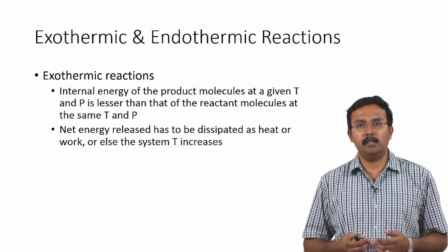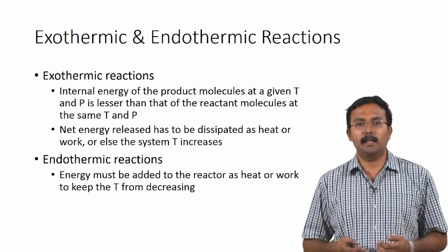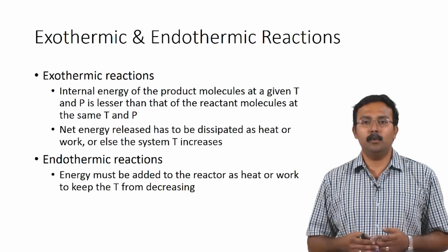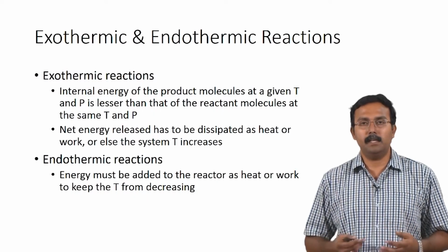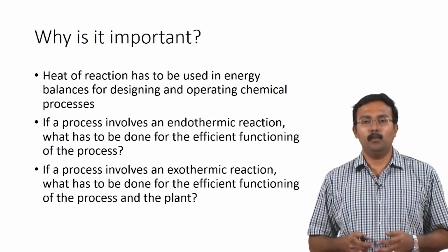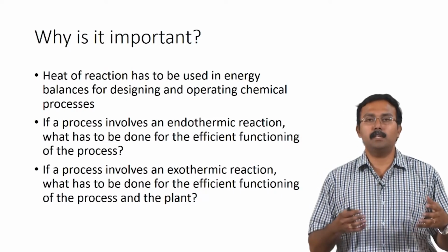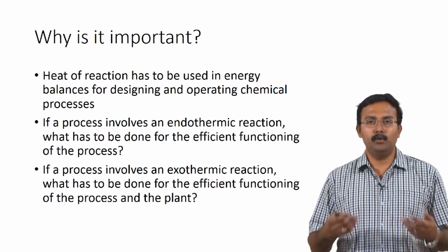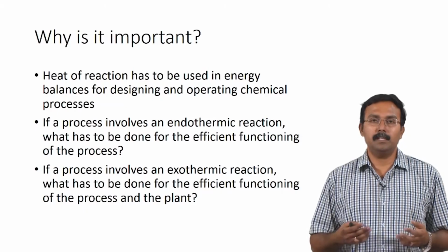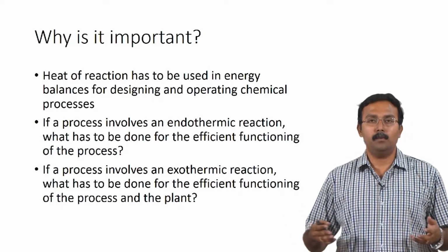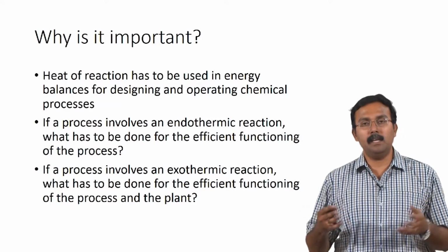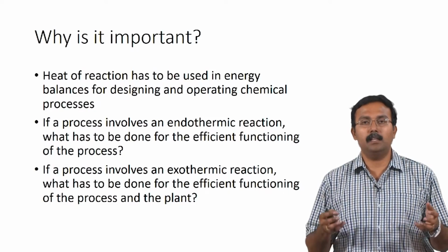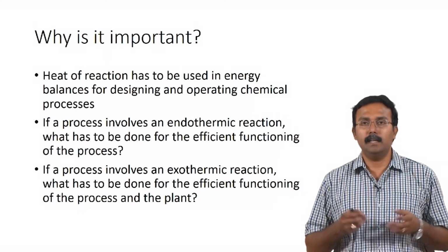If you have a process where you have endothermic reactions, energy must be added to the reactor as heat or work to keep the temperature from decreasing. Why is this important? Why do we want to maintain the temperature within desirable levels? For an exothermic reaction, if you do not cool it down, the temperature will keep increasing to a point where it can be a safety hazard or it can cause severe damage to the reactor and other equipment which is being used. So, that is a problem.